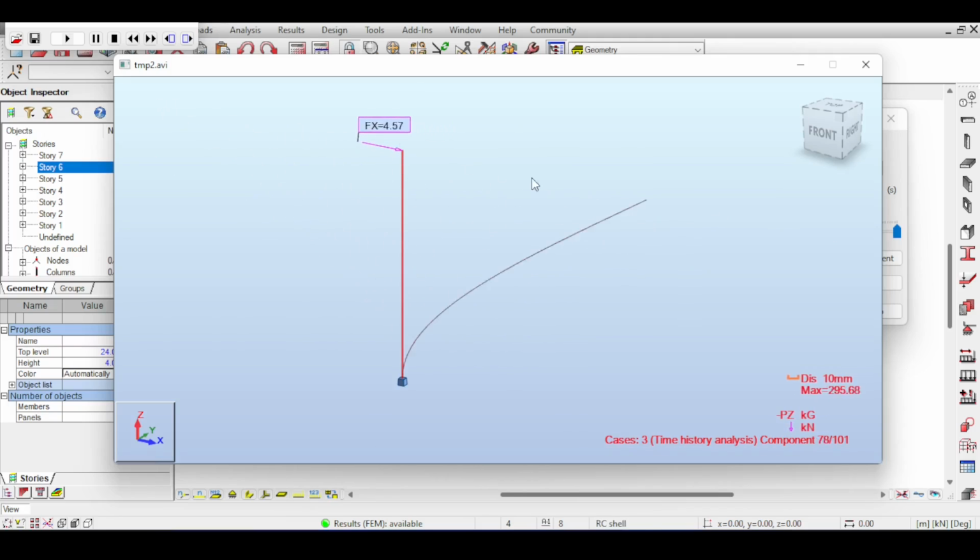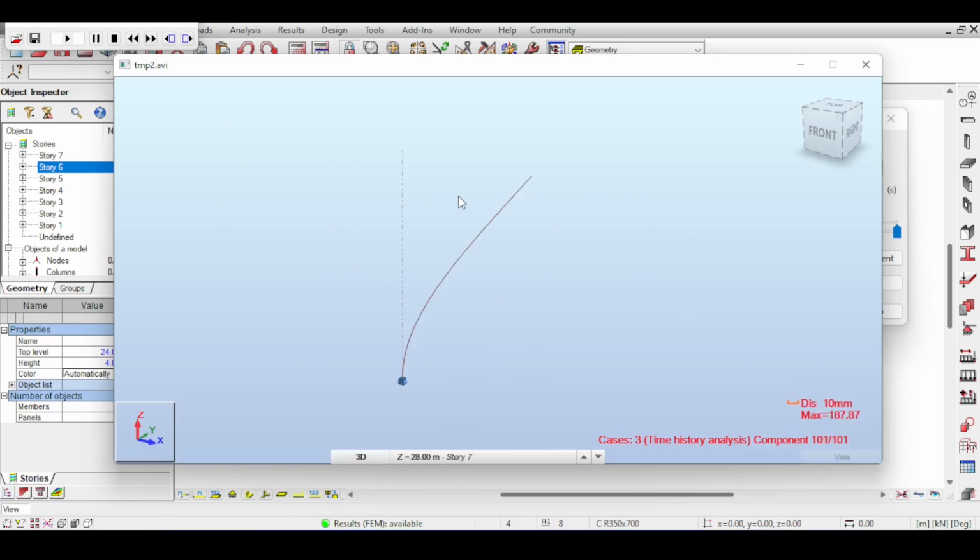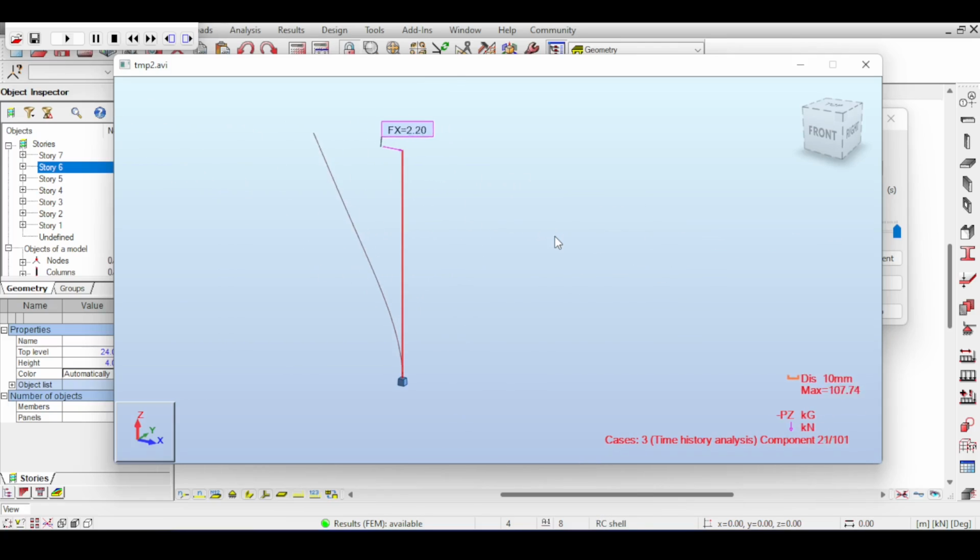And now the force is applied when it reaches the maximum. You can see that because the force pulsates exactly at the adequate time, the displacements build up, which is basic resonance. This is what happens when you use harmonics at 0.44. This is exactly what happens, but harmonics are basically a repetition of the force to infinity.